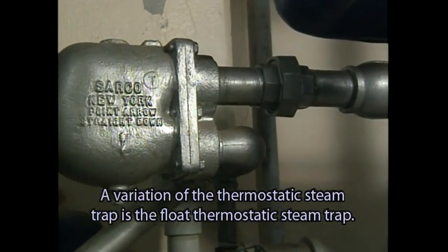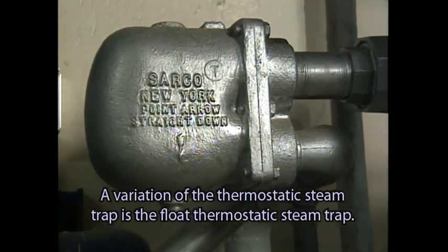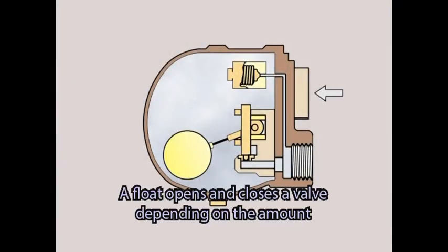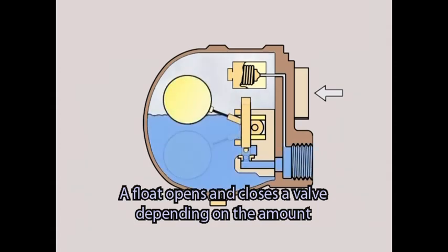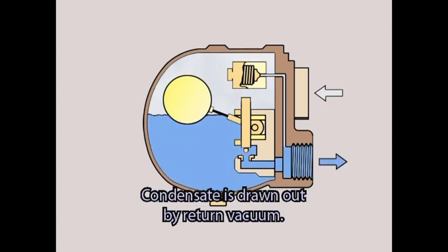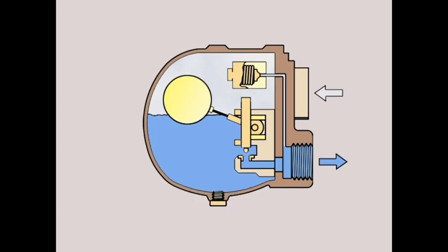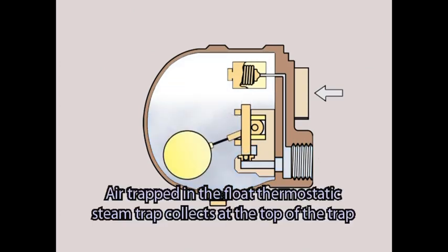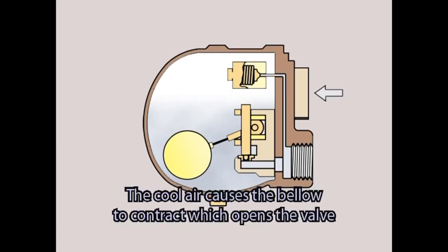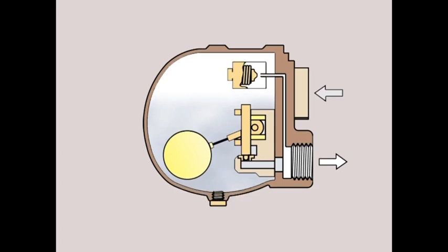A variation of the thermostatic steam trap is the float thermostatic steam trap. A float opens and closes a valve depending on the amount of condensate in the trap bowl. Condensate is drawn out by return vacuum. Air trapped in the float thermostatic steam trap collects at the top of the trap and surrounds the thermostatic bellows. The cool air causes the bellows to contract, which opens the valve to allow the discharge of air.